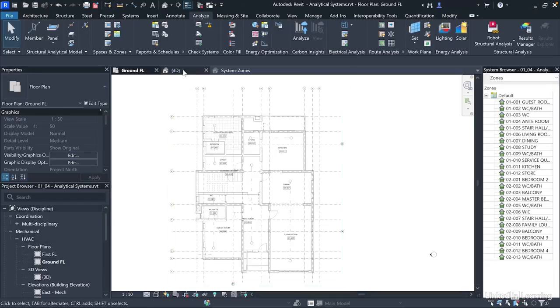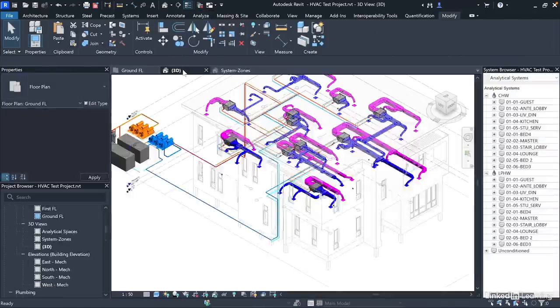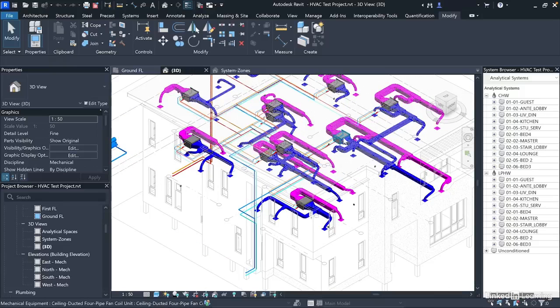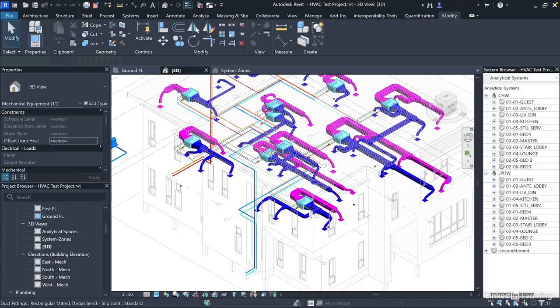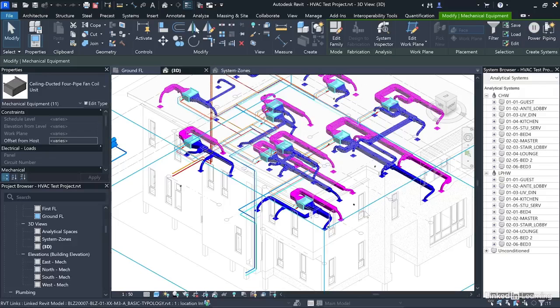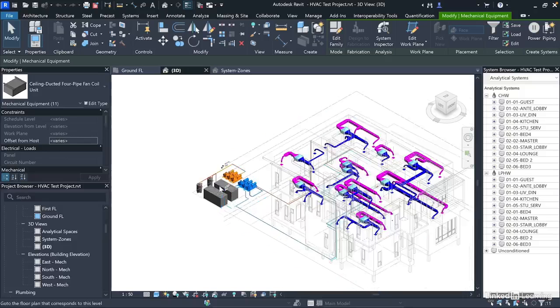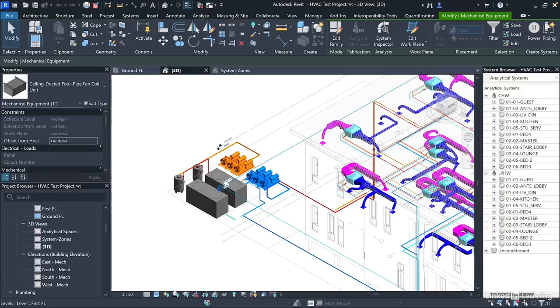Now going back to this sample project here, our design concept is an 11 zone fan coil system. So the primary pieces of equipment are 11 concealed fan coil units, which are the zone equipment, with a central chiller and a central boiler. So let's start by creating the outdoor units, which are the chilled and the low pressure hot water loops.